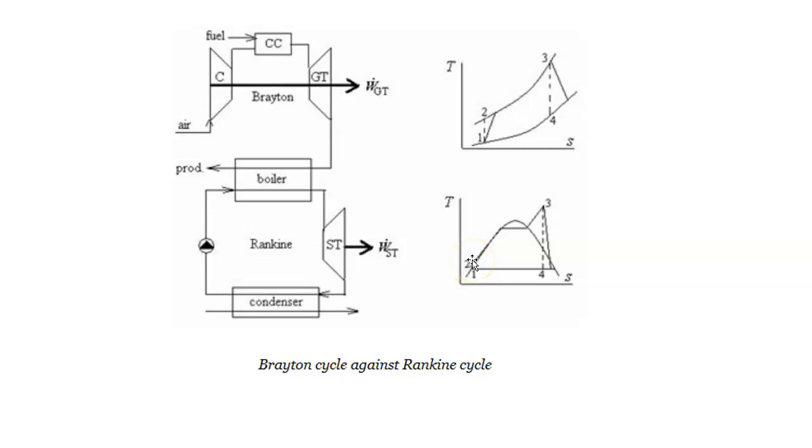And then in the economizer, there's a little more heat put into the Rankine cycle, which you can't see real well in here, but it'll extend the Rankine cycle out a little bit to give it a little more surface area. More surface area in this diagram will mean more net work, just like the Carnot cycle. The bigger the area, the more net work you are going to get.